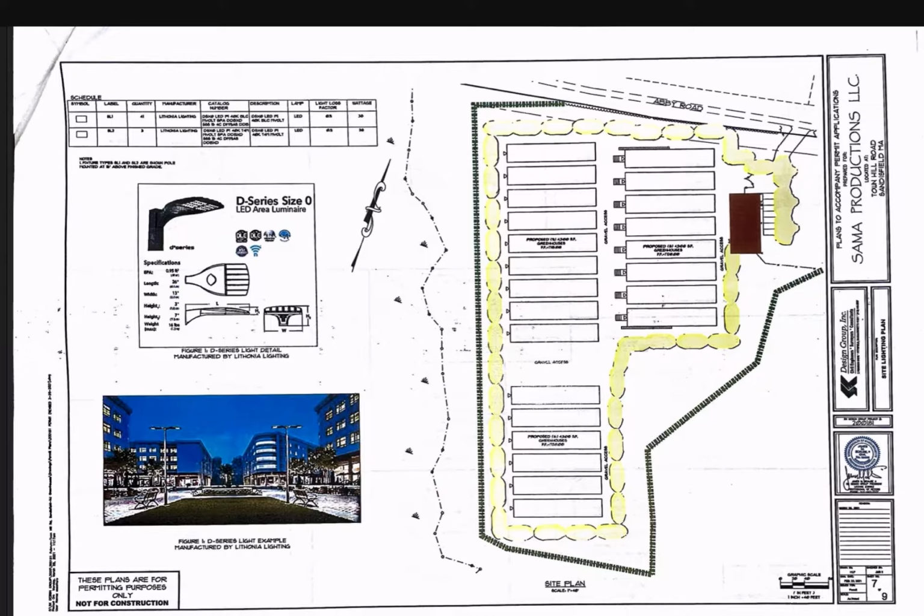If you put that in perspective, a well that puts out 10, 11 gallons a minute over 1,440 minutes a day would satisfy this project on its busiest, on its most intense usage. So you're talking 10 gallons a minute.